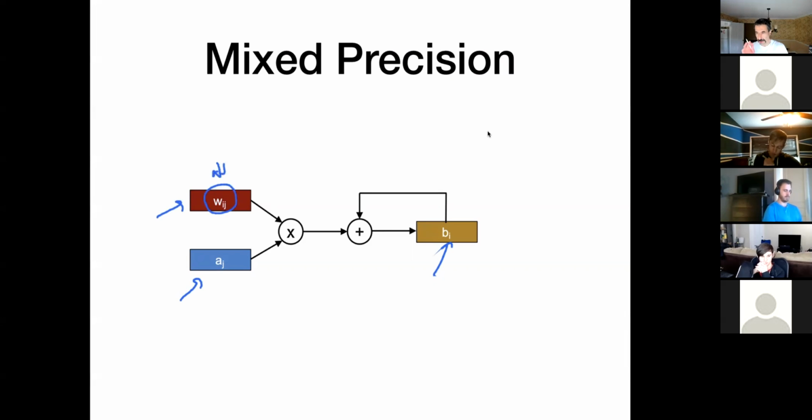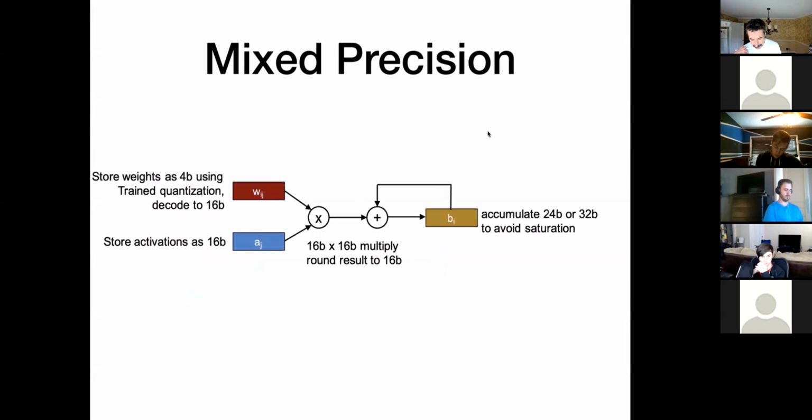For this, obviously, you need to access memory to retrieve your weights. And then you had this input activation, you need to multiply this, and then you need to add this together in order to calculate this output activation. So these are the operations that you have essentially for inference.